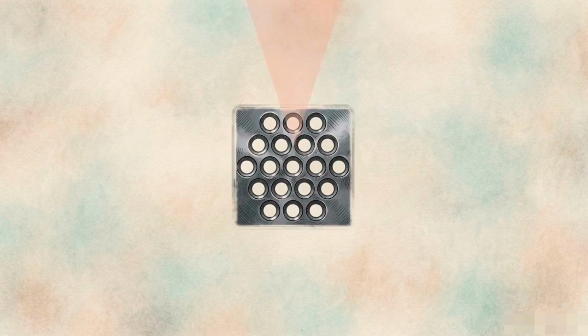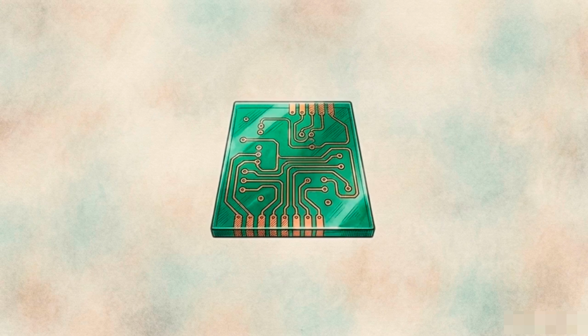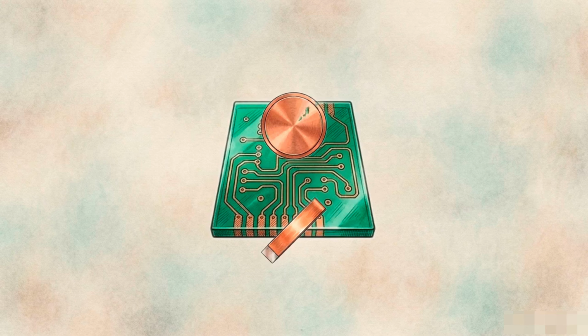This diagram shows a cross-section of a single antenna element. A copper wire, known as a microstrip transmission line, runs from a control chip and terminates directly beneath the circular copper patch. The terminal sends a 12 GHz alternating current through this wire. This means the voltage flips between positive and negative once every 83 picoseconds.